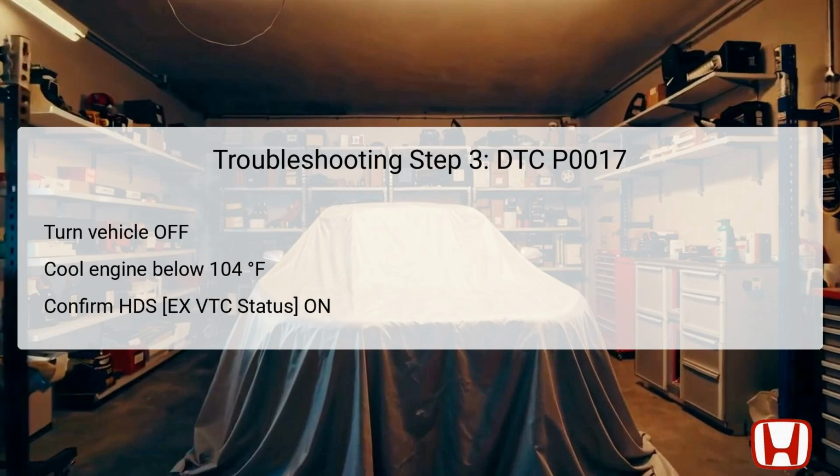During this idle period, watch for the status change, which reports the operational health of the VTC components. Additionally, monitor the HDS for the onboard diagnostic (OBD) status related to P0017 to identify any existing trouble codes, allowing for a comprehensive assessment of the vehicle's condition.